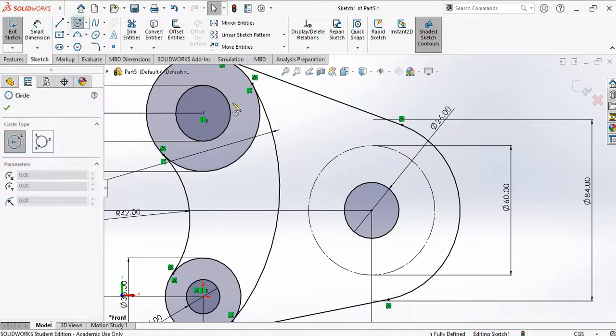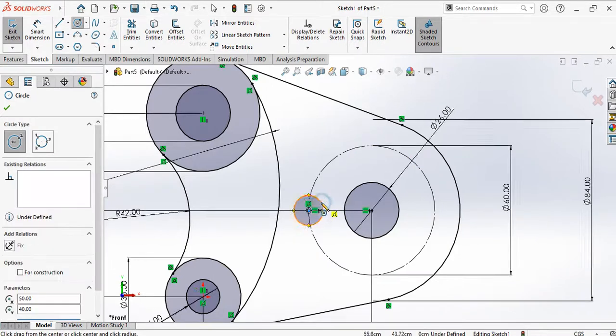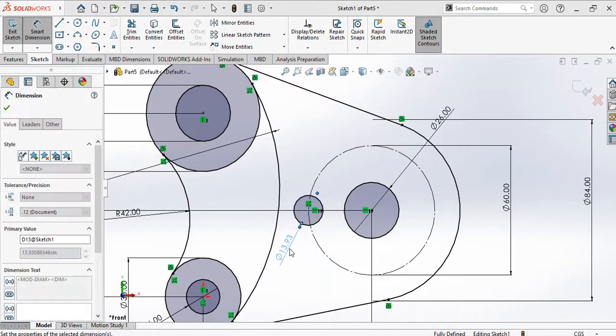Start center circle. You can touch the circle here. It will show you the positions 9 o'clock, 12, 3 and 6 o'clock. So we can place it on the yellow diamond shape here, at 9 o'clock. Then we place the diameter of 1.5. We place one circle first. Confirm.